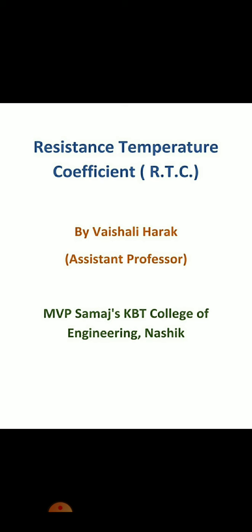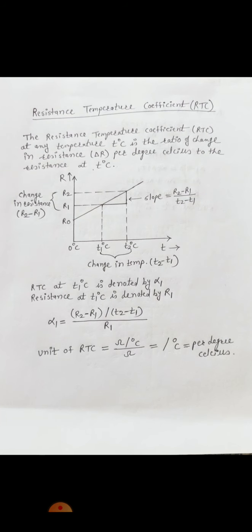Today we are going to discuss the resistance temperature coefficient, that is RTC. Now RTC is a factor by which the resistance of a material changes with respect to temperature. It is defined as the ratio of change in resistance per degree Celsius to resistance at T degree Celsius.